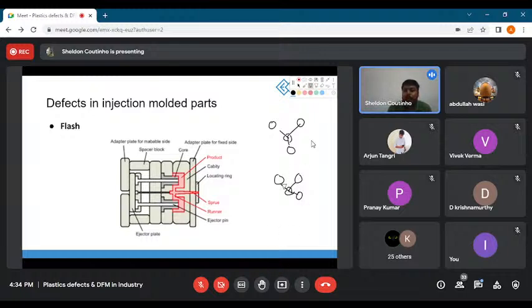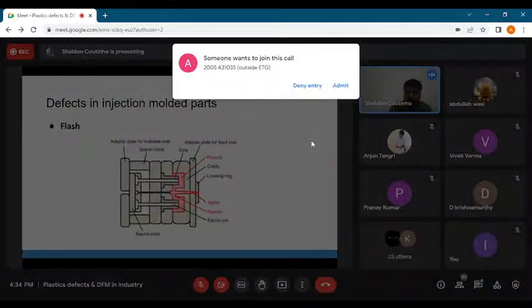So now this cannot be arranged, flipped. So the locator pin that's going into this can never go into this. However, the locator pin going into this one can go into this one, or can go into this one. So this is called foolproofing. So that is another way of foolproofing your device.